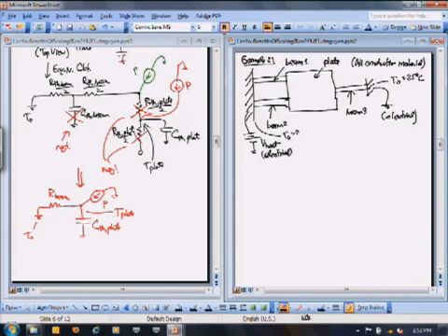What happens after I put a voltage across this? Current starts flowing, right? And we just saw from our little atomic clock example that when current flows through a resistance, there's Joule heating going on, right? There's an I squared R power that is generated that then is going to go into this structure. So by sending current through this, you are heating the thing, and this is one of the more interesting ways to heat up a micromechanical system. You just send current through it by putting a voltage across it.